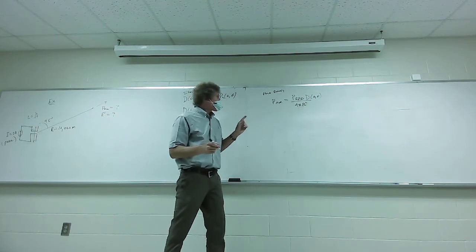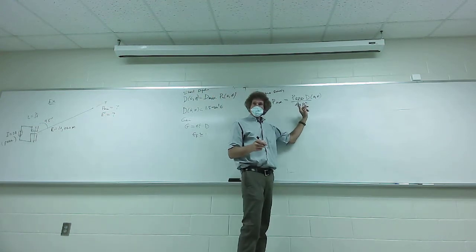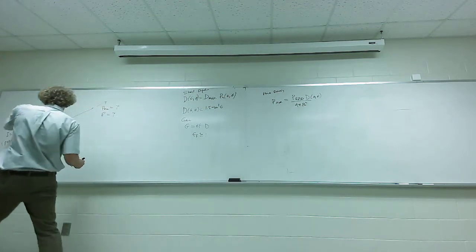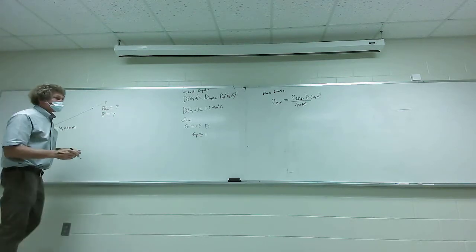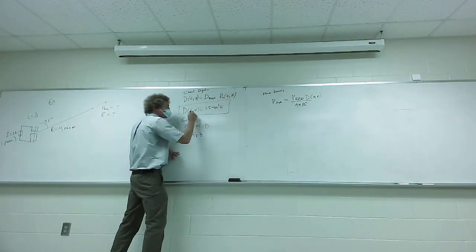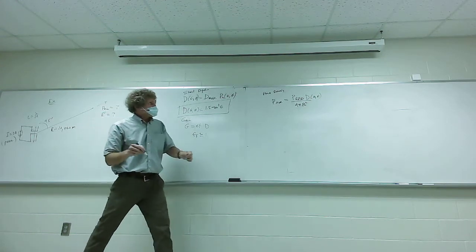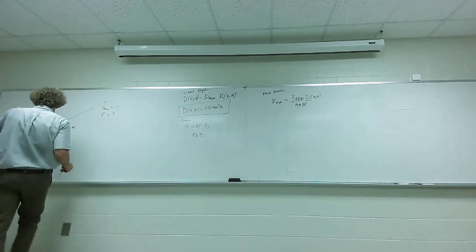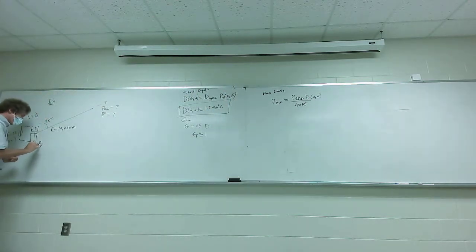Now here's the deal. For us, I gave you a short dipole by definition there. That means I know the directivity or the gain. You agree with that? But I don't have the radiated power, do I? I gave you the current, though. Do you remember? How would you get the power radiated here? Anyone? Well, what is power if you know current? What else do you need to know? You could say voltage, but yeah, that's right. In our case, radiation resistance. The radiation resistance has to do with the power radiated, go figure.